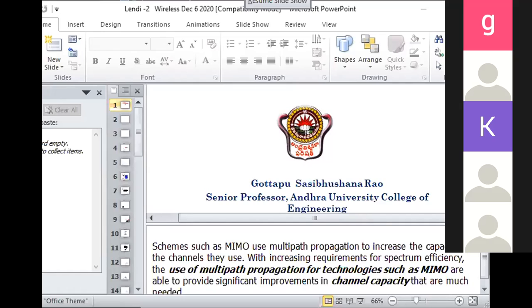For Wi-Fi also they are using 5 megahertz bandwidth. So depending upon the application, because Wi-Fi may not be able to cover the whole area, the cell coverage area is different. The population density and the number of users to be served is different from one application to another. The subcarrier bandwidth should maintain 15 kilohertz; the same subcarrier bandwidth only we use.